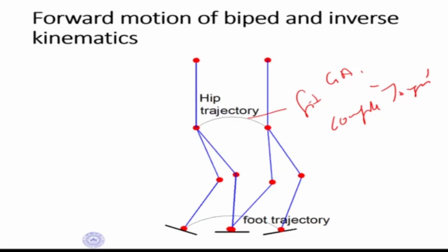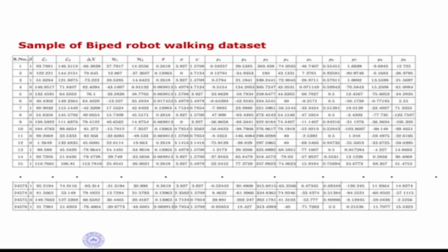By doing that for different terrain conditions, for example, going upstairs, going downstairs, going upside, going downside, GA can find what are the optimal hip and foot trajectories, energy optimal. Using that, it basically makes a database. This is the database, which is showing the turning angle, going up, going down, and the various parameters of the leg trajectory and the hip trajectory.